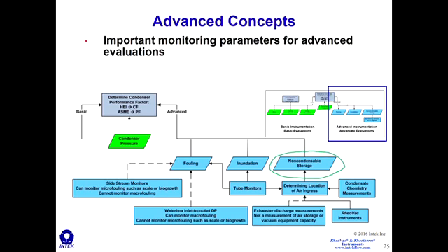Now, as we move over into non-condensable storage, there are different ways to monitor that. Almost every condenser gets shipped with rotometers on the discharge of their vacuum equipment, their vacuum pumps or steam jets, and you can measure the non-condensable flow rate leaving the vacuum equipment. And so that's one method. We highly recommend using a REAVAC instrument, and we'll talk about what that is. It's an instrument that goes between the condenser and your vacuum equipment, and there's a lot more useful information that you can get from this measurement, and we'll talk about that.